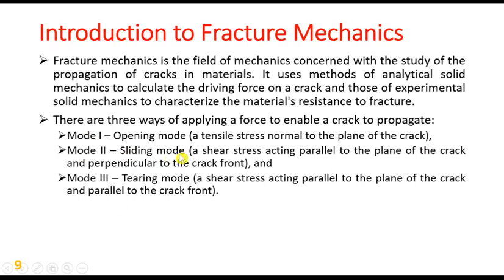Mode 2, sliding mode: shear stress acting parallel to the plane of the crack and perpendicular to the crack front. And the third mode is tearing mode: shear stress acting parallel to the plane of the crack and parallel to the crack front. Sliding parallel to the plane but perpendicular to the crack front is mode 2. If both are parallel, mode 3. And there are many other modes of failure, but fracture is very important nowadays and a hot topic for research.